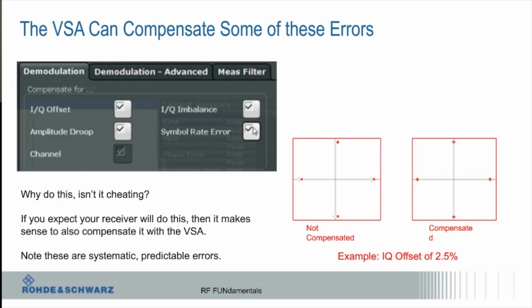It could have 11001, some random pattern, and you'll get a statistical distribution of this variation, right? So that's called data-dependent jitter. But if it's a periodic signal, I can look at it as phase noise, and it's really the same thing.